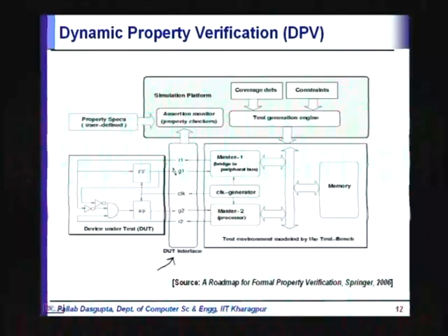So, my signal R1 here may be called as REQ1. Okay. So, the binding is telling us that R1 is REQ1 here, and on this side maybe this is called as Z1. So, we are saying R1 is Z1. Okay. So, that is how you bind the thing together, and this interface is what is made visible to the assertion monitor.